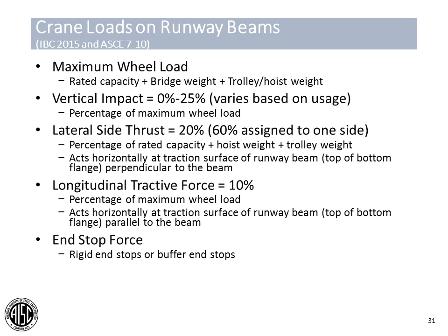The longitudinal tractive force, again, is due to the inertial effect of the entire bridge crane system moving along the length of the runway members. And this is specified as 10% of the maximum wheel load, according to AISC 7. Again, this is due to the maximum wheel load because the bridge beam itself is moving in this direction. Again, this force will act horizontally at the surface between the end truck and the top of the bottom flange of your runway member.